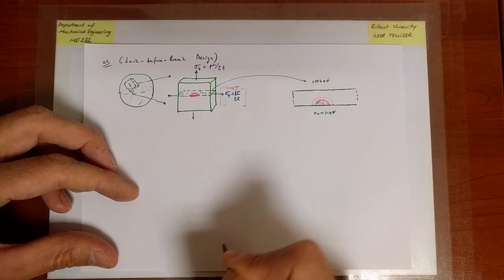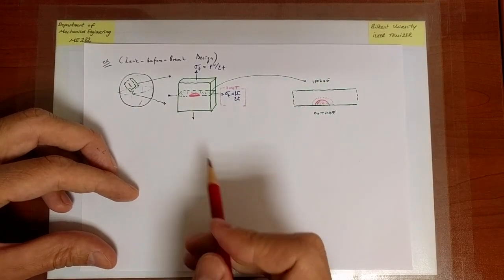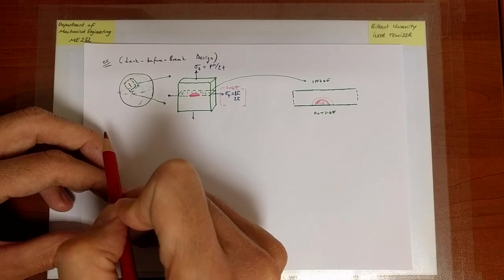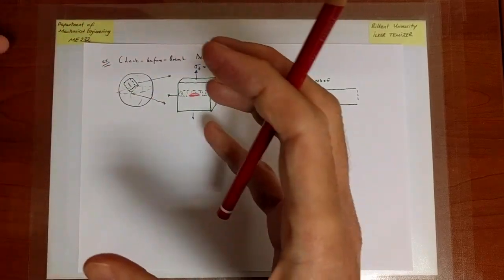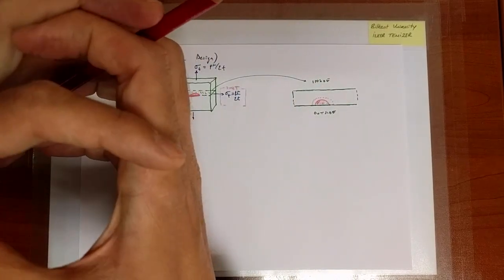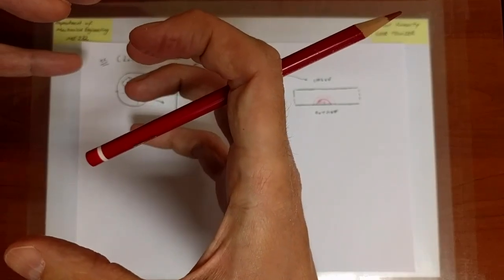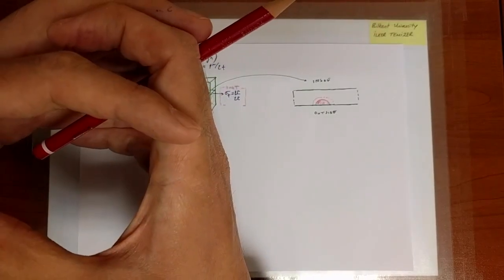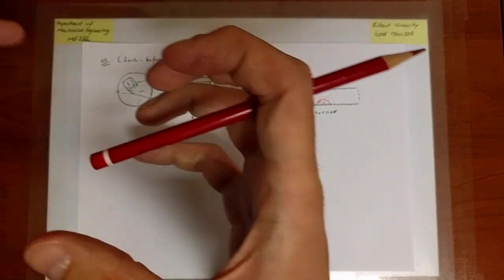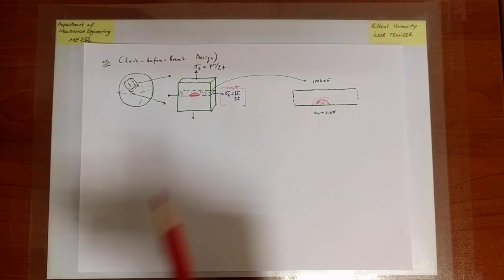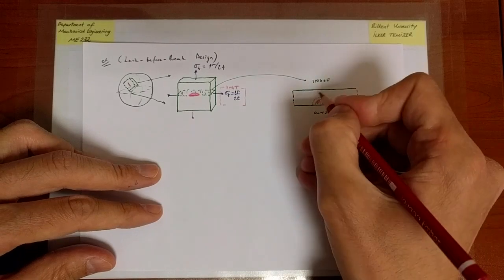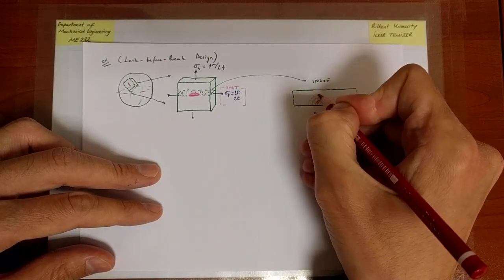This happens in particular if there is cyclic loading of that pressure vessel. So for instance, you remove the gas inside, you transport it, it gets unpressurized, and then you pressurize again to transport gas again, unpressurized, you remove the gas, and so on. You fill, empty, and then each one is a cycle of loading. So at each stage, the crack will grow.